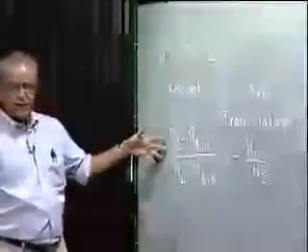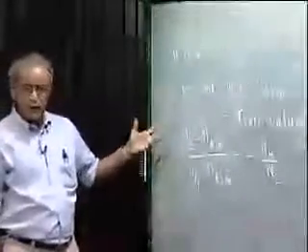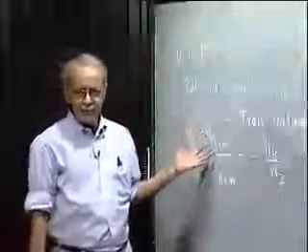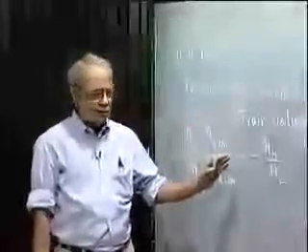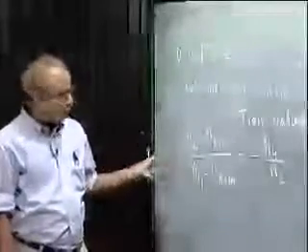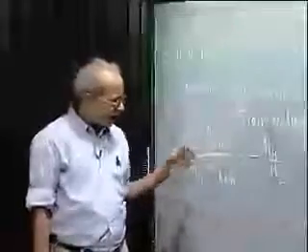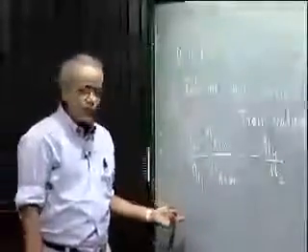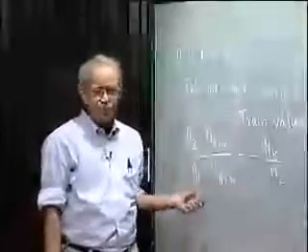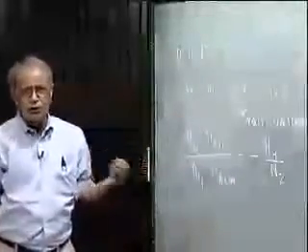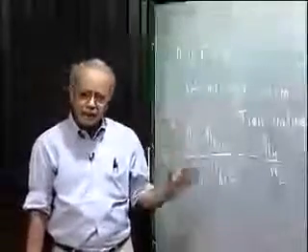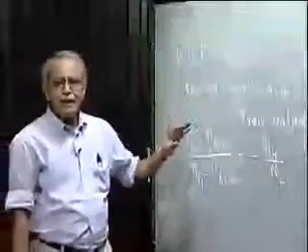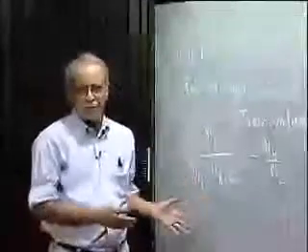And we shall use this for a tabular method, which I also explained, where we talk of two conditions. First, we lock all the elements to the arm, then give the arm a particular revolution, then lock the arm and give one of the gears some other revolution and calculate the revolutions of all the elements. Then add these two, we get equations in terms of two unknowns, and with two input speeds specified, we will be able to solve for those two unknowns, and all other speeds are expressed in terms of those unknowns, so we should be able to determine those. This we shall see in our next lecture through examples.